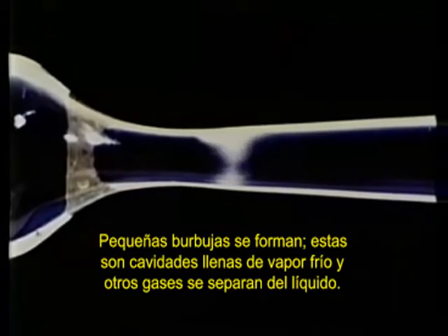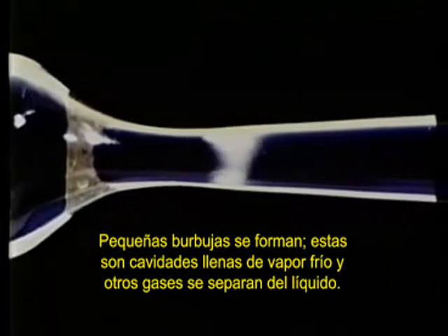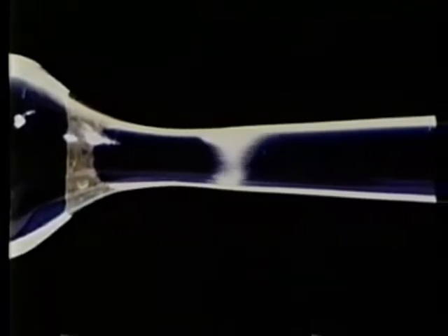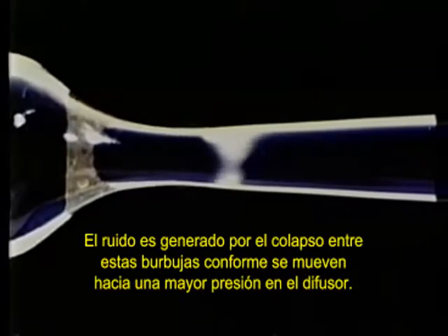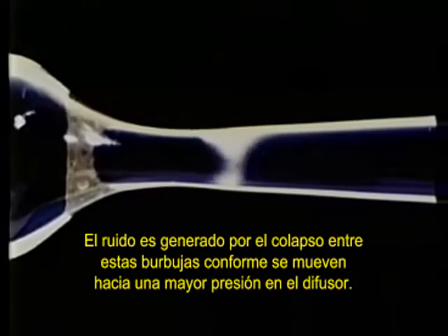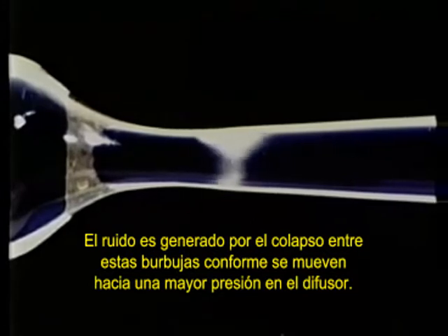Small bubbles are formed. These are cavities filled with cold steam and other gases diffused from the liquid. The noise is generated by the collapse of these bubbles as they move into the higher pressure in the diffuser.